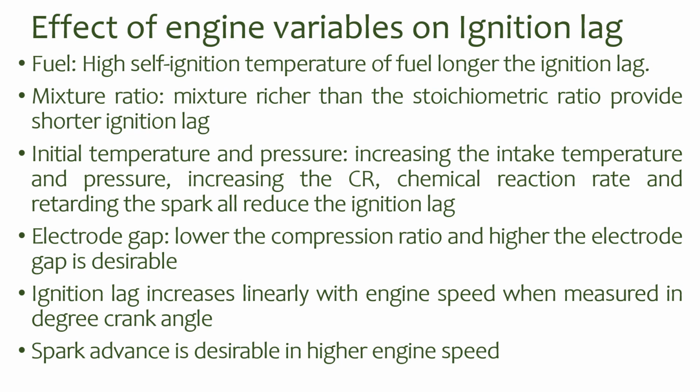And lower compression ratio and higher electrode gap is desirable for SI engines. And ignition lag increases linearly with engine speed when measured in degree crank angle. Spark advance is desirable at higher engine speed.